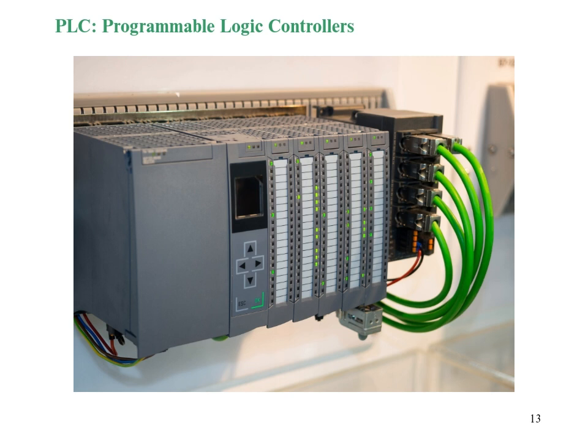Within the PLC, they have the most important four things: input module relays, as I said relays are nothing but switches, output module relays, and CPU and memory. Fundamentally, PLCs can be thought of as a cabinet consisting of thousands of relays, counters, timers, and memory cells. As you can see, this looks like a cabinet, right? And this is a PLC.